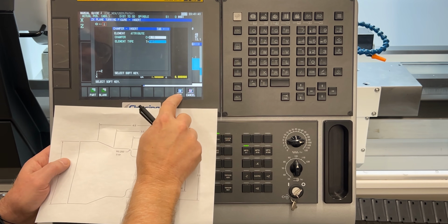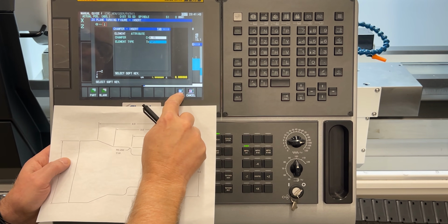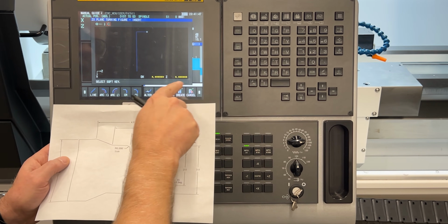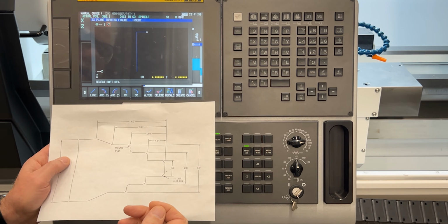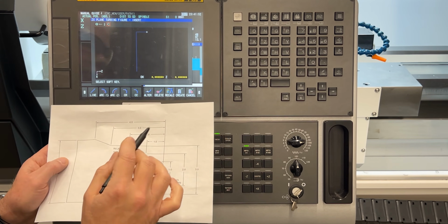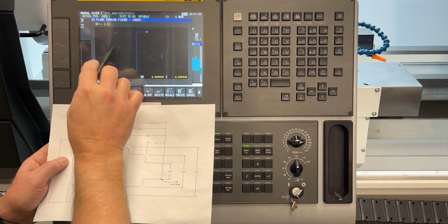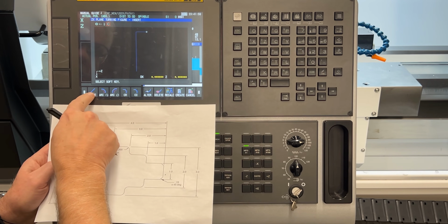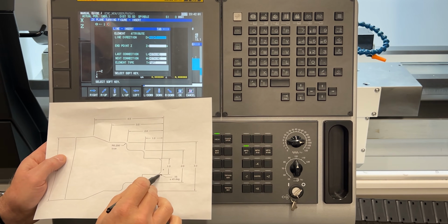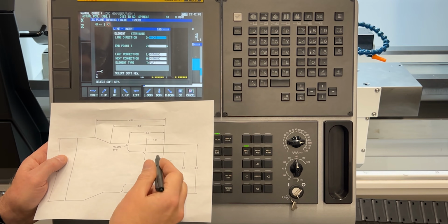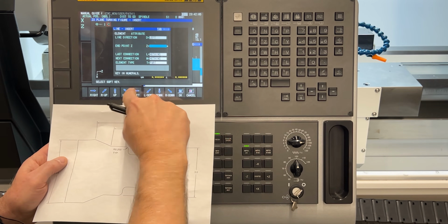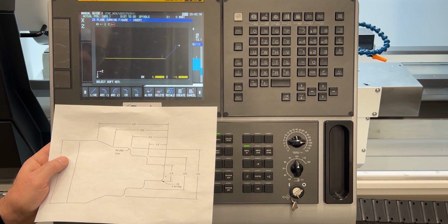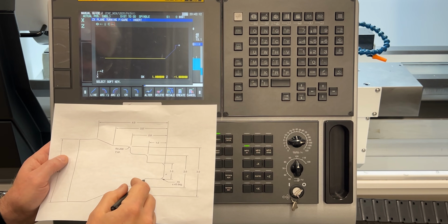And it's still the part that I'm doing, and I'm going to select OK. Now, these go to asterisks because it doesn't have an endpoint. It's being calculated, so it won't show the chamfer until I give it another move. So I'll hit the line moving again, and I'm going to go from there back to Z minus 1 inch, and select OK. And so now the chamfer shows up.